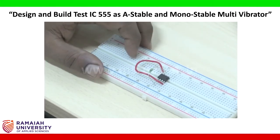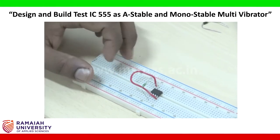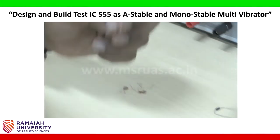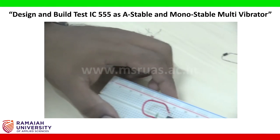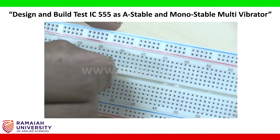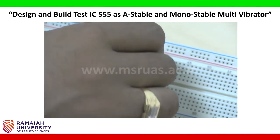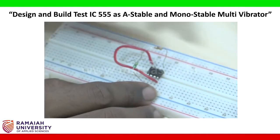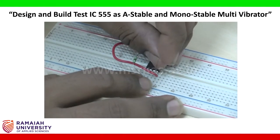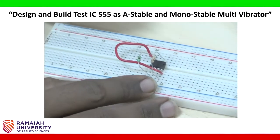Next, to connect pin number 2 with pin number 4 or pin number 8 with a 10 kilo ohm resistor, I take another 10 kilo ohm resistor. This is pin number 2. Pin number 2 I need to connect, that will be shorted with either 4 or 8. I am going to short it with pin number 8. So here it will be connected.